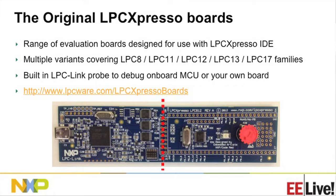We've again got a built-in link on here. It's slightly different in implementation, but the same basic principles. We can debug the onboard MCU, or in this case, we actually need to cut the tracks between the two halves of the board, and then we can use the debug connector there to debug, again, an off-board MCU. You can do that very simply with just getting a Stanley knife and cutting the tracks there. Or in some cases, people go to more extremes and actually physically chop the board in two.